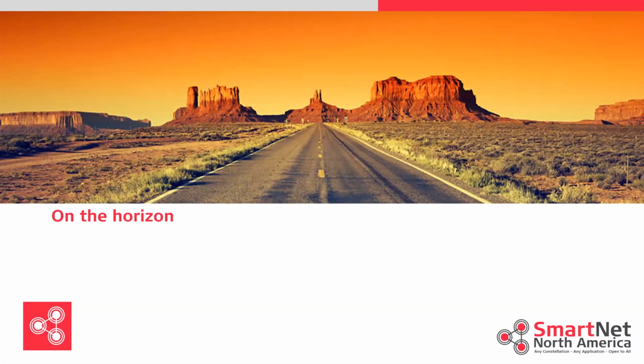Everything being shown is East Coast or West Coast. What about mid-US or even better, Texas? How does it affect us? It affects everyone. Literally everyone needs to be cognizant of broadcast coordinates changing. If you are a SmartNet user, you need to be cognizant that the broadcast coordinates of a station could change. Will it change? Maybe. Again, we'll address that in a second, but you need to be cognizant. Yes, it's going to affect everyone. How much will depend on the exact station. So that is going to be the tricky part.